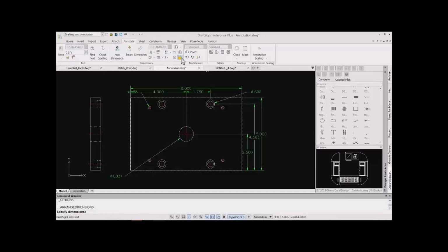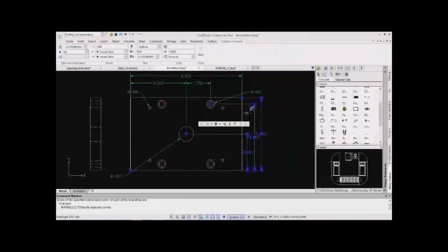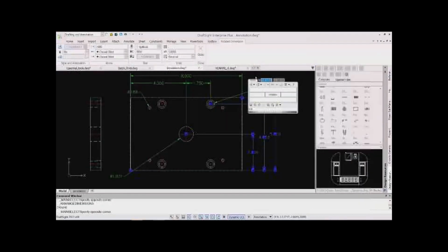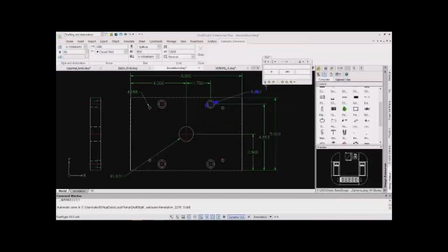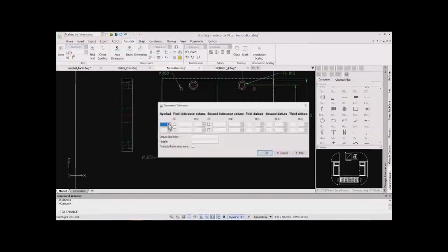The dimension palette eases our work by giving us options to define limits, fits, precisions, and many more, and to modify dimensions. We can then save settings as favorites and utilize them when we need them. We always keep some tolerances for dimensions, and the tolerance functionality helps us to precisely define a geometry and makes production ready drawings. So this is how we can give tolerance values here, which helps to precisely define geometry and make production ready drawings.